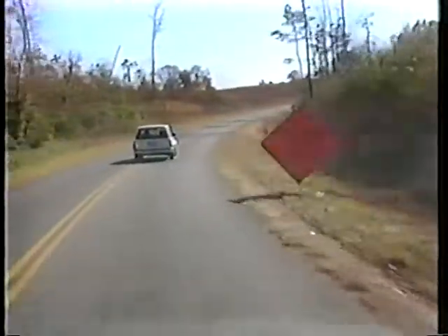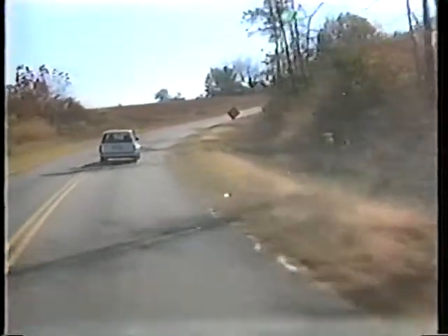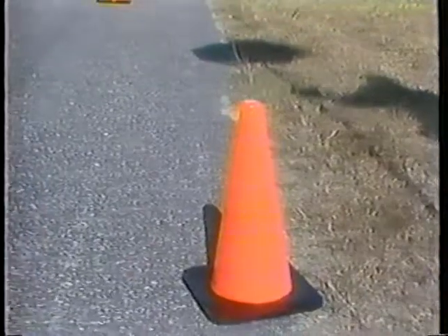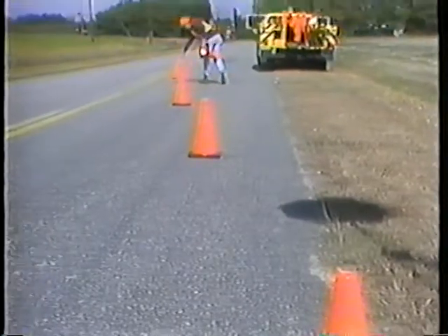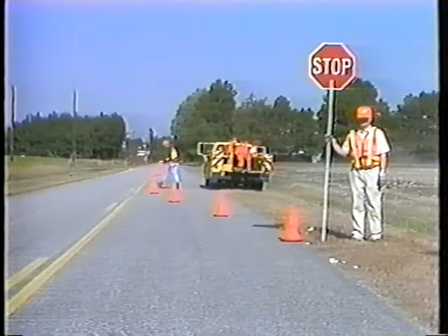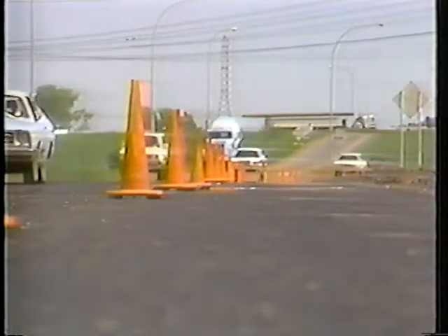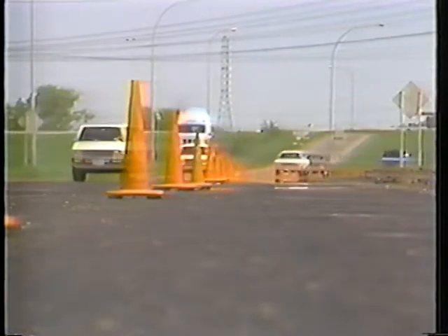If restricted sight distance is a problem, for example, a sharp vertical or horizontal curve, the taper should be moved well in advance of the obstructed view. Beginnings of tapers should never be hidden behind curves. Traffic should be observed to see if the taper is working correctly. Frequent use of brakes and evidence of skid markings are indications that either the taper is too short or the advance warning is inadequate.